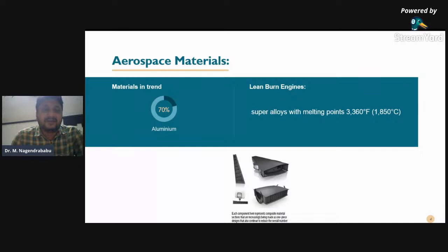Unlike any other industry but oil and gas, which also has high temperatures, pressures, and corrosion requirements, aerospace materials themselves impact component design. Design for manufacturability, or DFM, is the engineering art of designing components with a balanced approach, taking into consideration both component function and its manufacturing requirements. This approach is applied more than in other industry component design, because these components have to accomplish certain loads and temperature resistances, and some materials can only accommodate so much. Materials and component design truly drive one another, as opposed to one following the other.